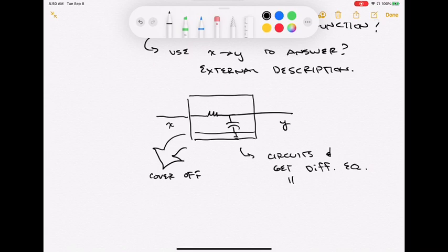I could still find, in this particular case, right, I've got an R and a C in here. This is a low pass filter, and if I know the value of R and I know the value of C, I can figure out where the cutoff frequency is. So I can still verify that this was a low pass filter. I just can do it in a much more precise way, in a much more methodical way, and a much more transparent and complete way, if given the choice.